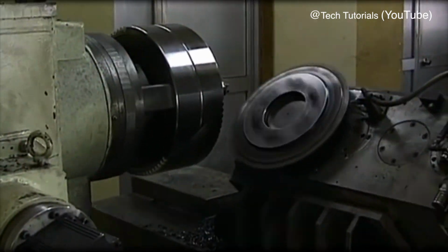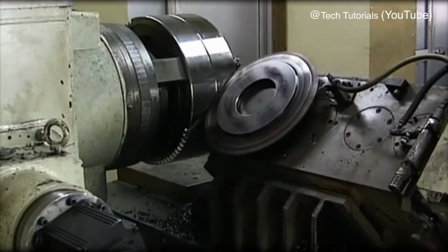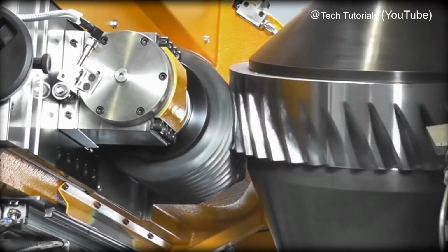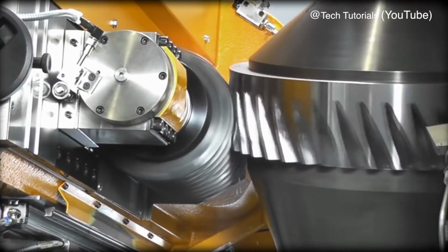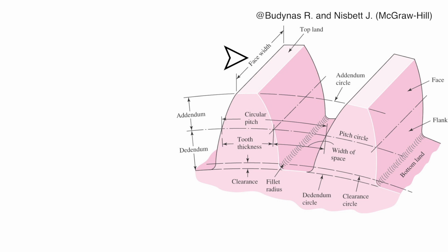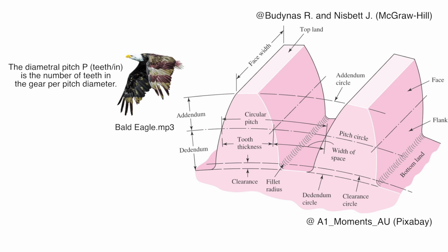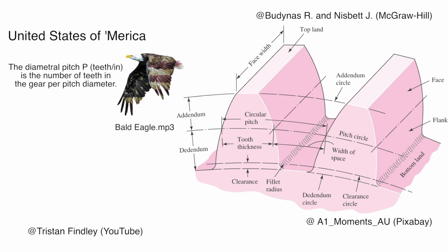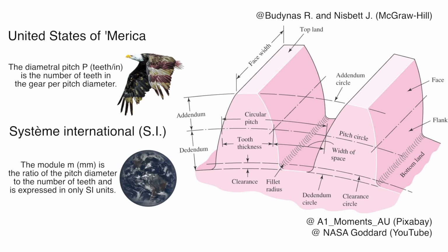Gears are generally manufactured through the process of hobbing a gear. When manufactured, there are 3 principal measurements one should keep in mind. Gear thickness, which along with material determines the maximum amount of force a gear can transmit. Pitch, or the distance between points on teeth, diametral pitch here in America and module everywhere else. And finally, the number of teeth.